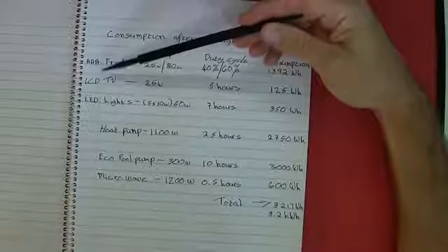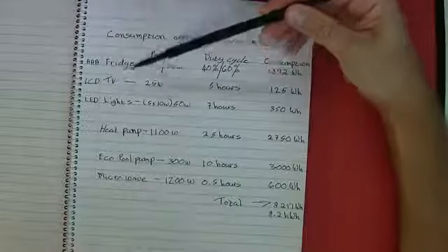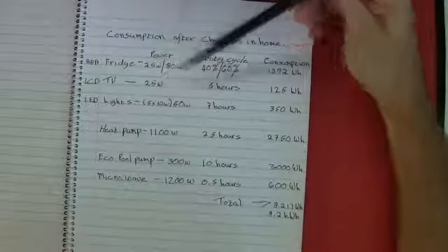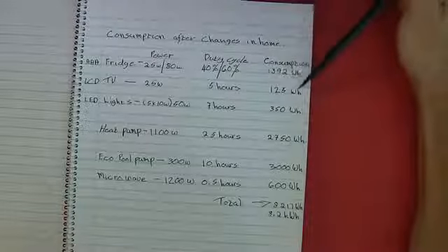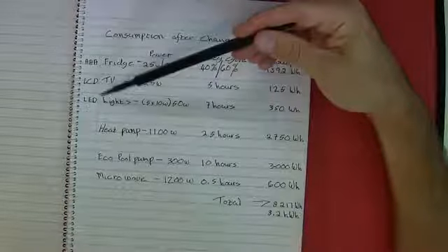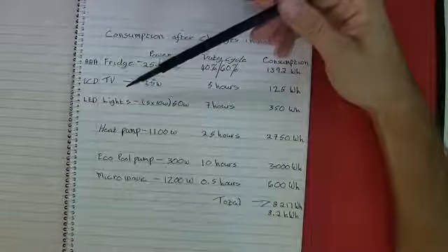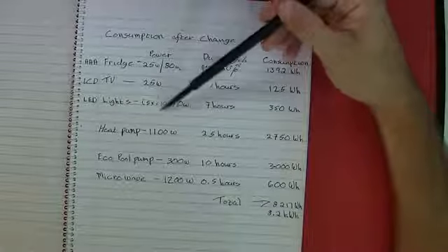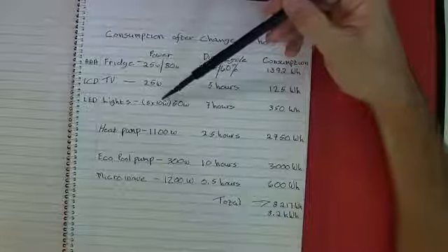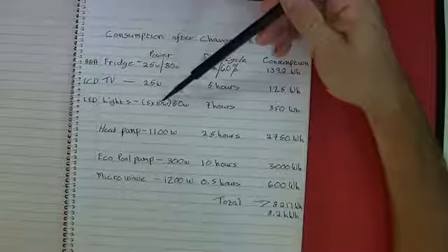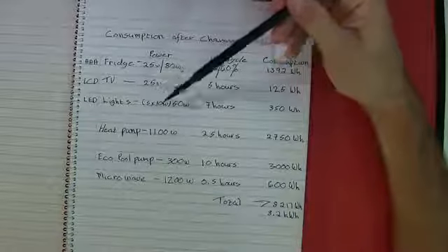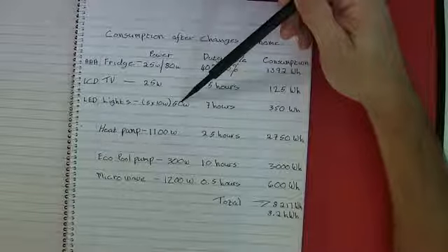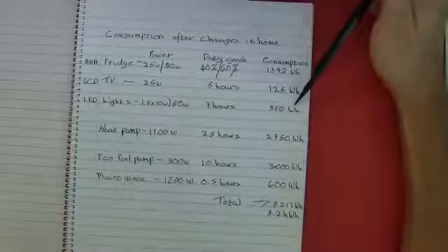A TV: if you go to these new modern LCD TVs, for an equivalent size TV, you could drop from 80 watts down to, let's say, 25 watts. And that would then bring you down to 125 watt hours. If we change those downlighters from 50 watt downlighters to, let's say, 10 watt downlighters, and I'm being quite generous here because you could drop below that, but let's say you want some good lighting so you don't want to go to a 5 watt LED, you're going to go 10 watt, still, that's a fair saving. You're now going to be using 50 watts as opposed to 250 watts, so that goes to 350 watt hours.